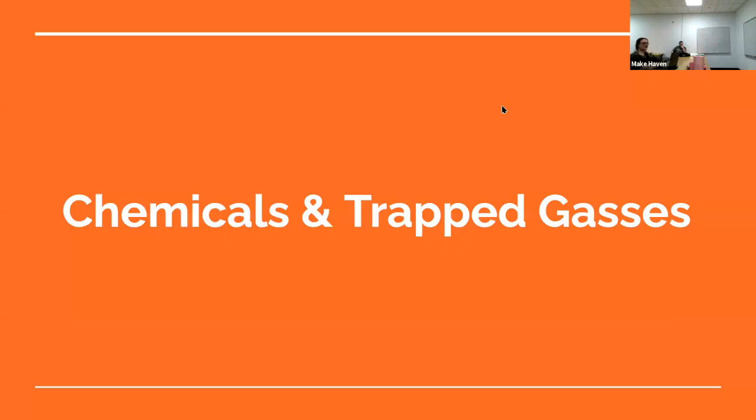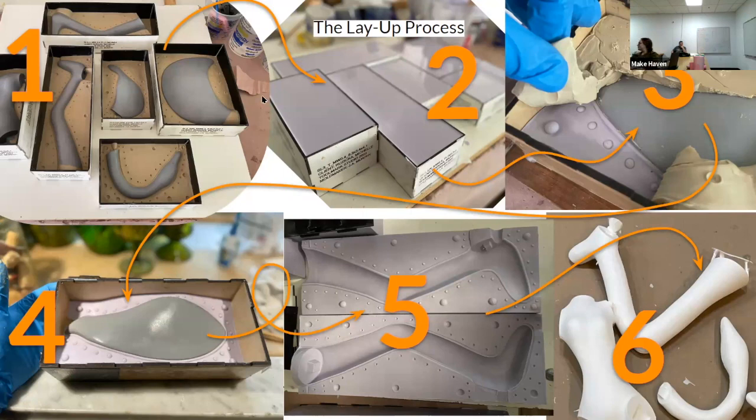You said something about the exact halfway mark, and I'm trying to see where something gets sunk in halfway or poured in halfway. Well, what it basically is, if you imagine a blanket of clay, if you were to squish the part straight down, depending on the topology of the piece, it might or might not actually hit the halfway mark. So you end up tooling the clay up to that line all the way around it. You can't exactly see it here, but the clay is following along that midpoint rather than the other way around.